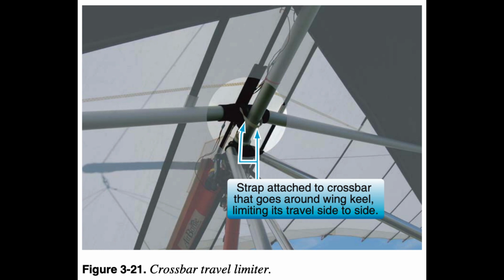Another less commonly used method of increasing trim speed is to increase tension on the crossbar by pulling it back further, slightly increasing the nose angle and reducing twist. This increases the angle of attack, AOA, of the tips, producing more lift, and it lowers the nose to a higher trim speed. This is a typical in-flight trim adjustment for high-performance hang gliders. The roll control is diminished with this faster and stiffer wing. Ground adjustable trim systems are described in the Pilot's Operating Handbook, POH. For each aircraft, different loads may require different pitch settings.